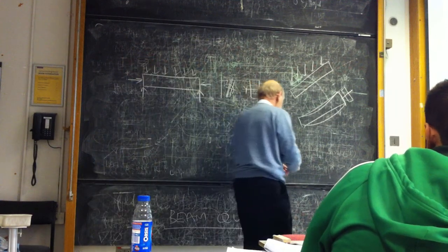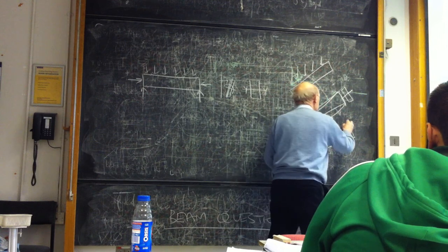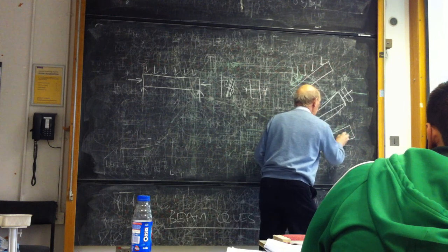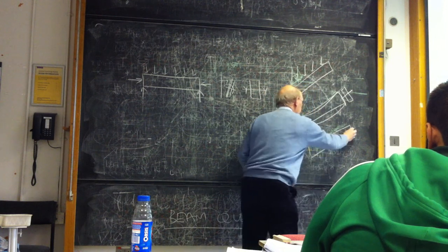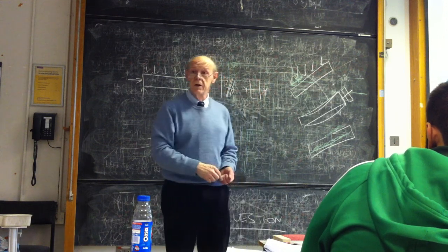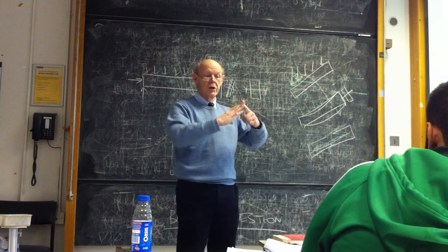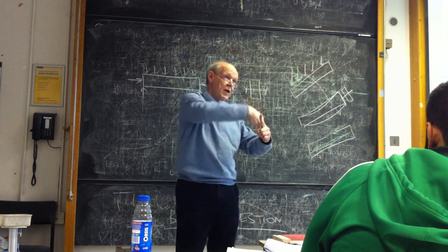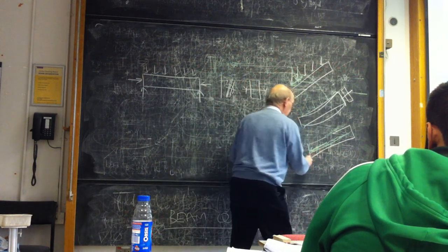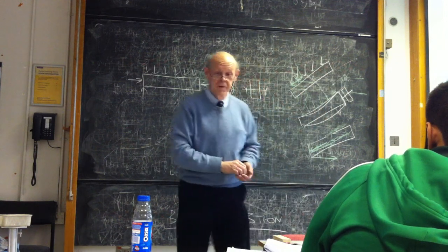But in addition to that, I'm going to have a series of loads down the slope, which are actually, I've drawn them there, but they're actually, I suppose, in here. So I'm going to have a gradually increasing compression down the slope, which will be quite substantial. It's the sort of thing you get in, as soon as you put timbers into a roof and make them into an arch. Not merely do they bend, but the weight actually acts down the slope, which is why, incidentally, you've got to make sure you tie the bottom together. That's why it does that.